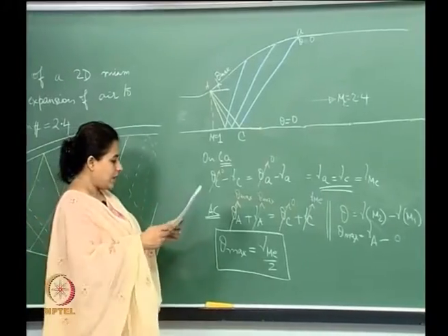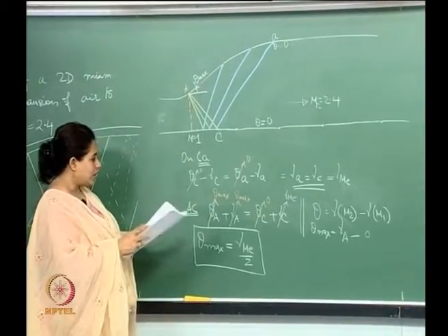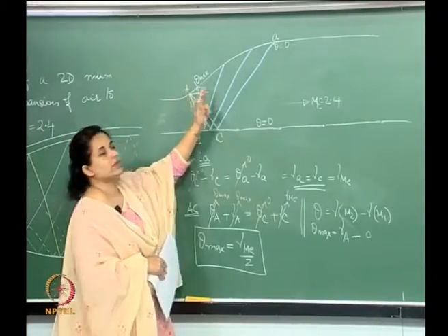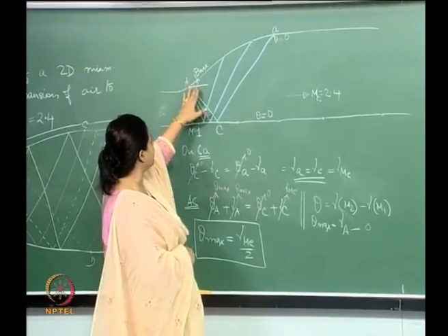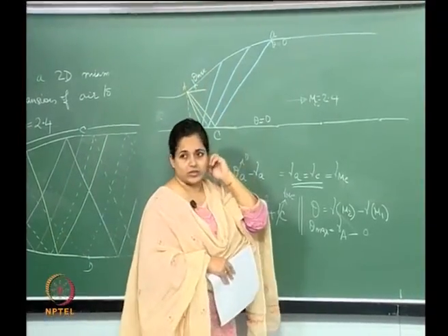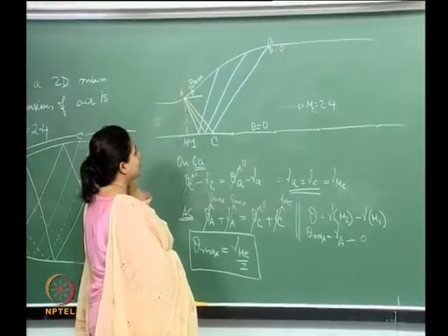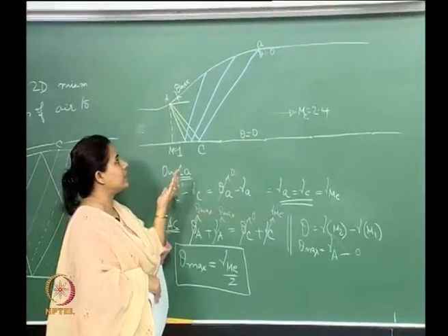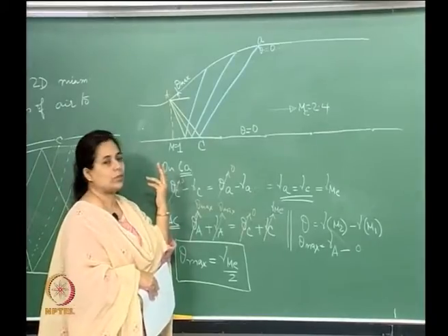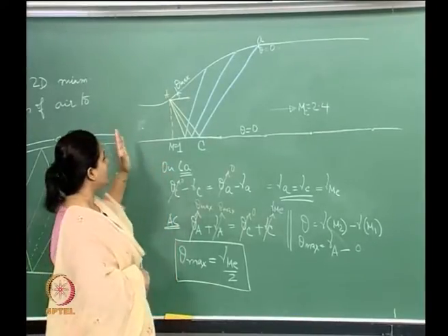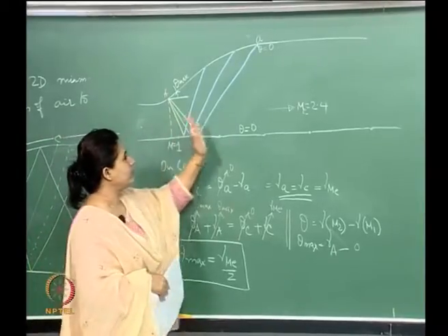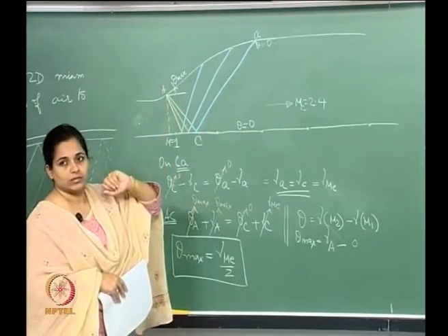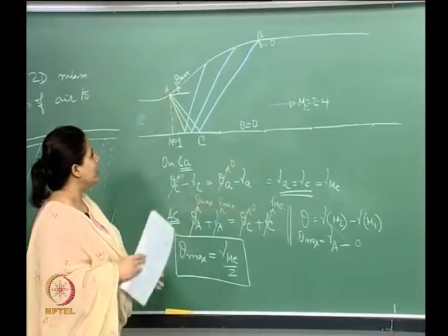Essentially what we are saying here is that you need a minimum length. You can start from theta max and gradually go up and straighten it out. So you need this minimum theta max, and if you decrease the length below this, then it will not be shock free, then you will have shocks. So to have shock free parallel flow, based on this Mach number, this is the minimum length you need. This is the length that we shall be needing.